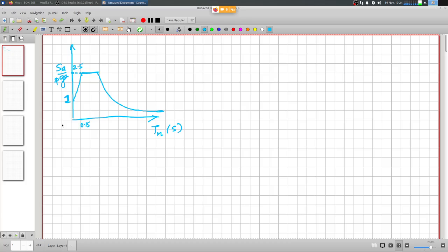In case the fundamental period is very small, smaller than 0.15, of course then the higher mode periods would be smaller still. So for that situation, this flat curve has to be used.